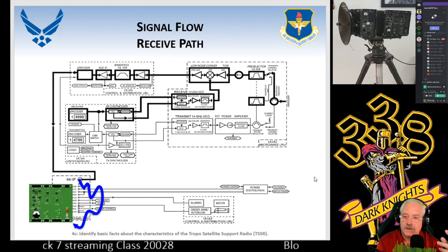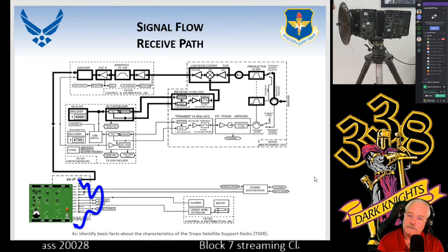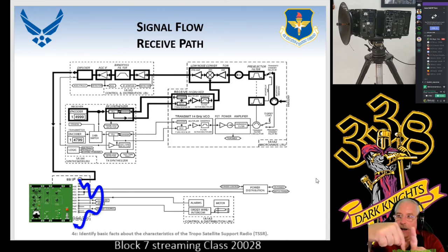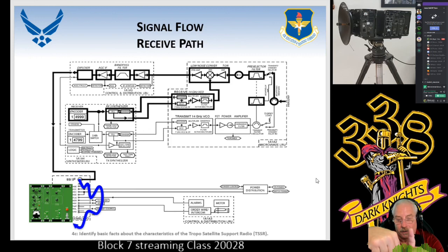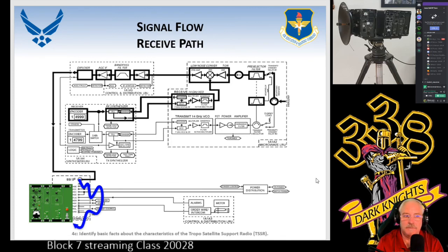So one side you have baseband and 70 megahertz, the other side you have both. And the idea is to keep them separate when they come in and when they go out, if that makes sense. I like to call it a two-way highway on that 2-foot or 150-foot cable, because that's what it is. You got the 70 megahertz going this way and the baseband going that way. So you have 70 megahertz, you have the aggregate, all on the same line.